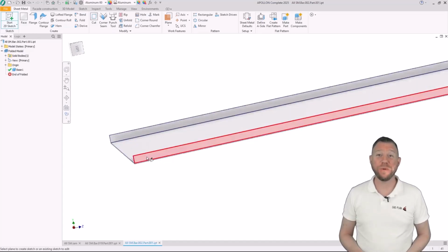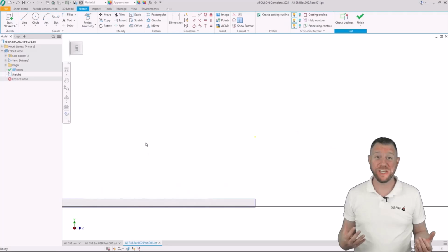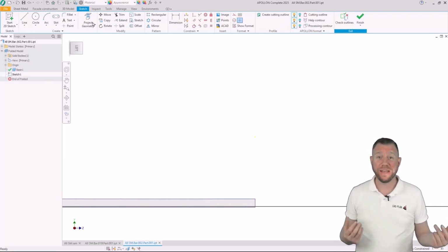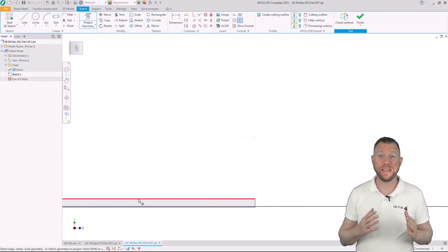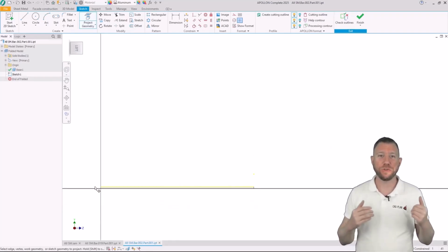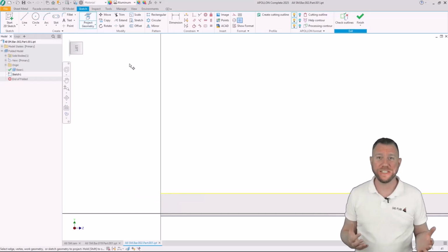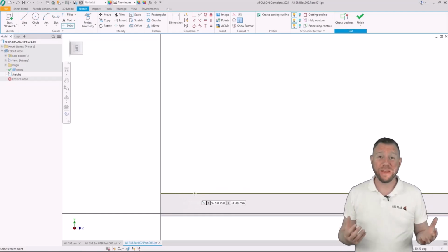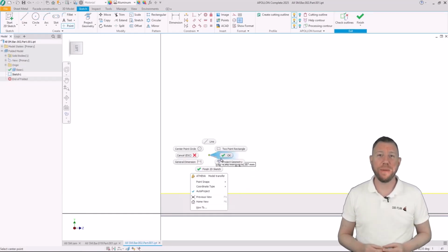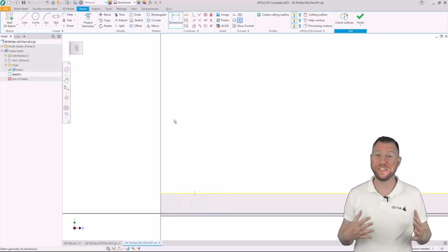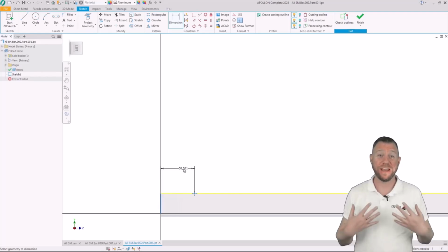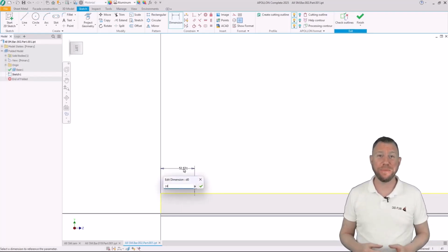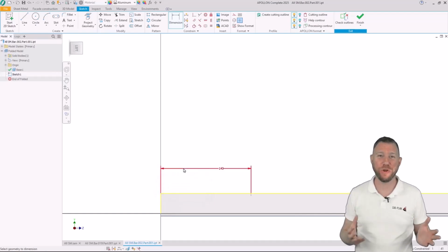In the next step, we carry out the cleat punchings directly in APOLLON. Here again, parametrics play a central role. Using parametrics, this processing can be defined quickly, easily, and reliably. You specify the required dimensions and then apply the desired processing directly to the component. This allows the cleat punchings to be adapted precisely to the structural requirements.